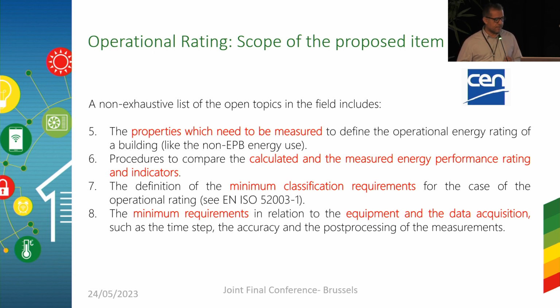Also, we are trying to introduce some elements which refer to comparison between asset and operational rating. There are some studies in the literature which reveal what is more or less the relation between the two assessments, the two ratings. We wish to introduce some procedures in the standard which will be used in order to assess the performance of the two different ratings. And another aspect, in a similar manner as with the ISO 52003, is that we also wish to introduce some elements concerning minimum requirements for the operational rating.